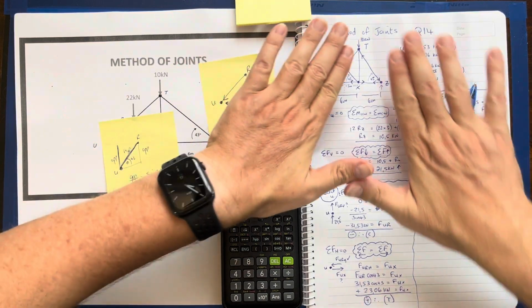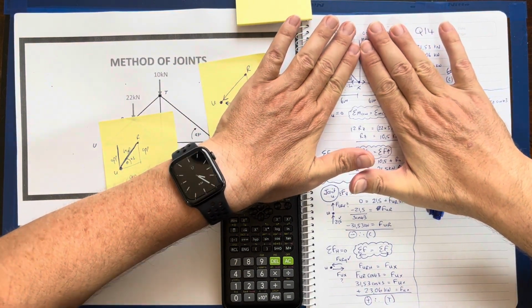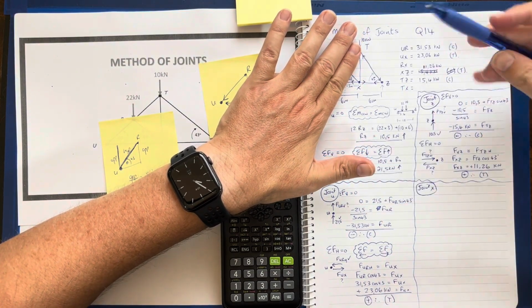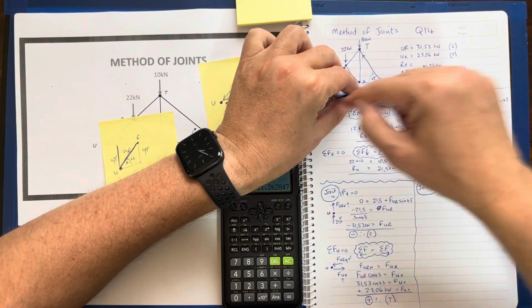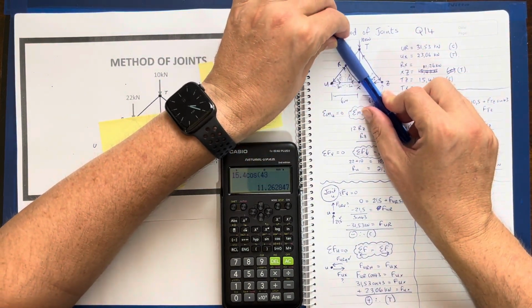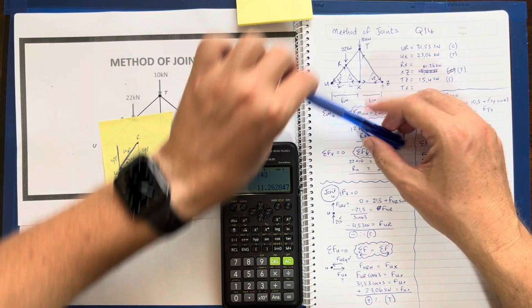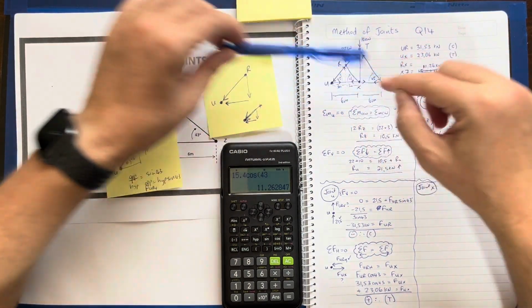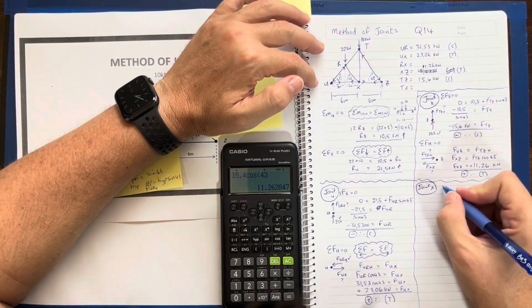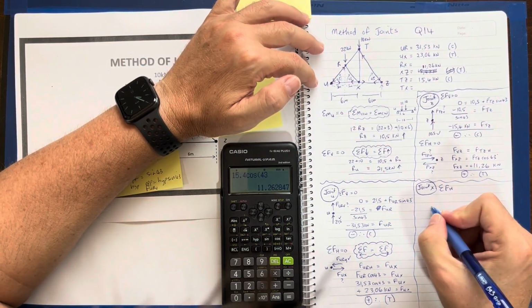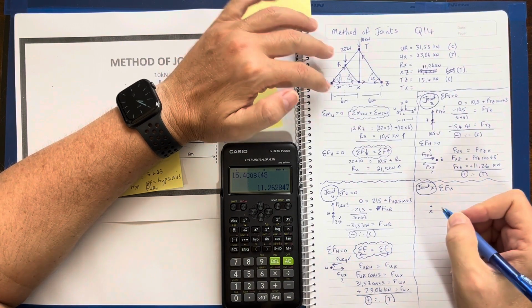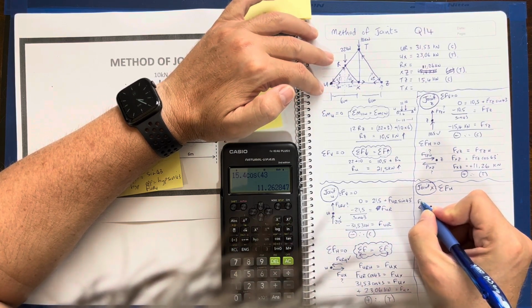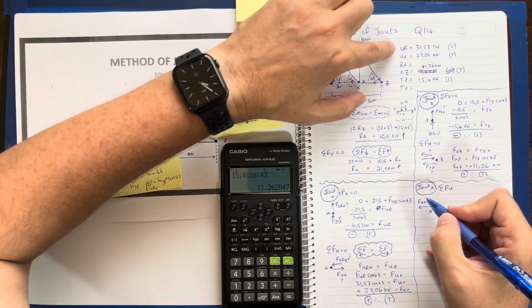Remember, we isolate everything around the joint, and if I'm going to do horizontal work, I am only going to work with forces that are traveling in this direction. I resolve angled forces or axial forces into horizontal. I can't with this one because it is perpendicular. So it'll be that one to there, and I've got that side and that side. So let's draw that. I'm going to go sum of my forces horizontal, and I'm going to draw X here. What do I have? Straight away I can see I have force UX. I know what that is.